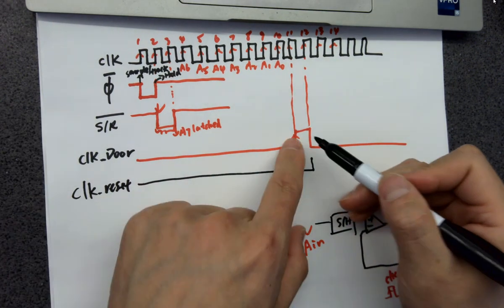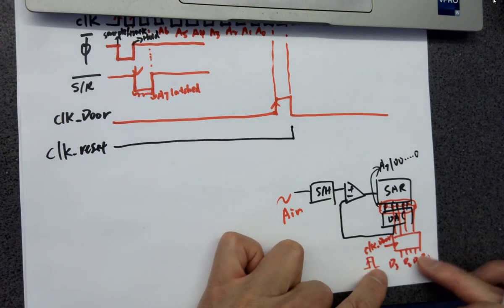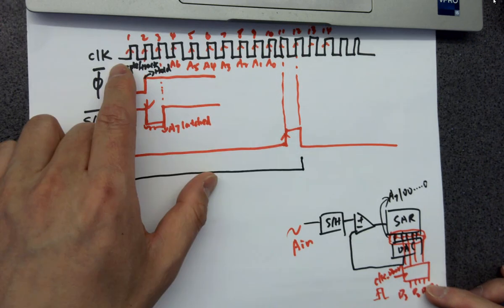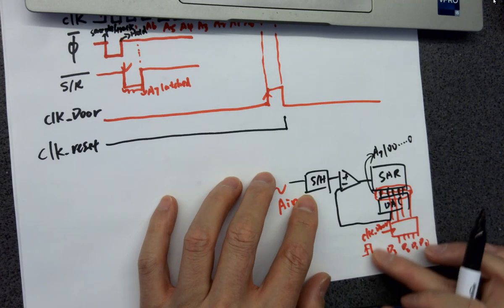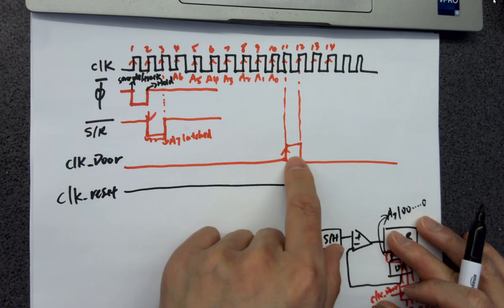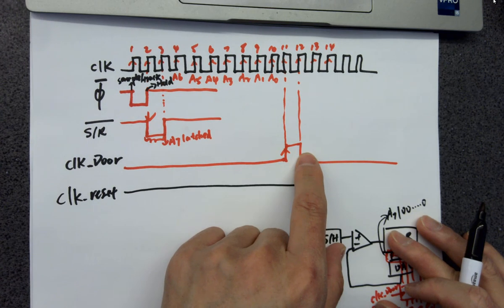So after that clock, the final output is being kicked out to here, being latched to the output. So we get a first analog data point converted. Since it's already latched over here, we don't have to worry about that anymore. And the clock can also be seen becoming 0. It's a memory, so nothing can be changed.